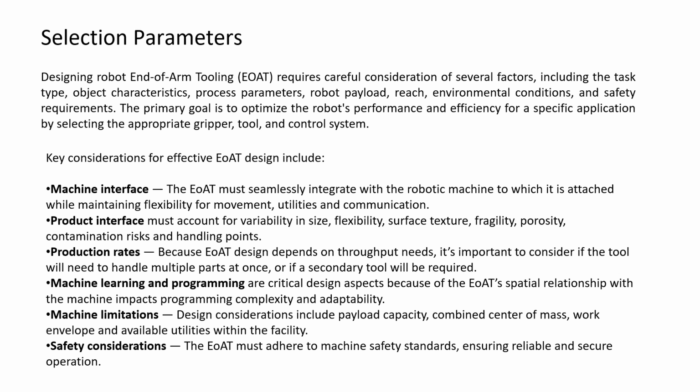Then the product interface must account for variability in size, flexibility, surface structure, porosity, and contamination. Whenever we design the end of arm tooling, it will have direct contact with, let's say, the product. So we need to take care that it should not damage it, and at the same time it should accommodate variations in sizes. According to that, we might need to have changeable end of arm tooling or something that can accommodate different sizes.